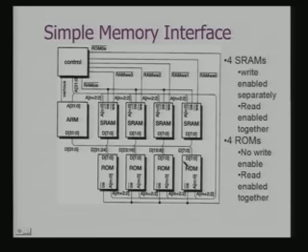Now, if you see the address buses, the way it has gone in, this is a 32-bit address, and this 32-bit address is fed to the controller as well as to these RAMs, because this address has to be decoded by these RAMs to select the individual rows. The decoding logic is part of this SRAM module.